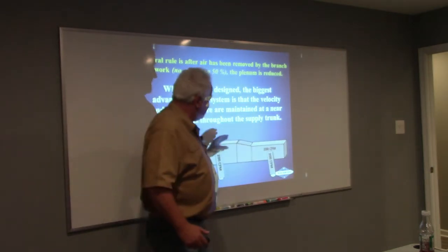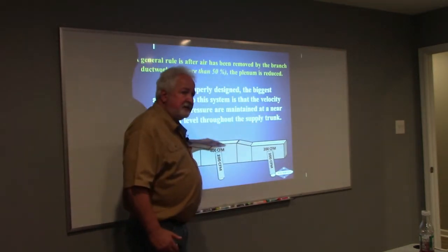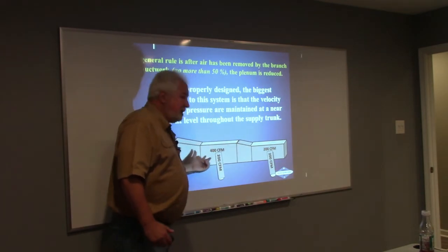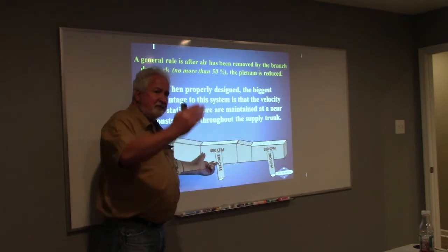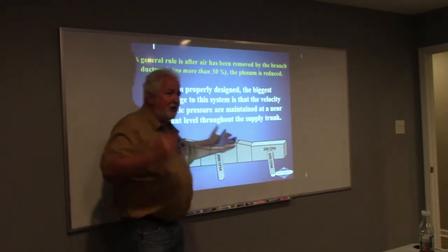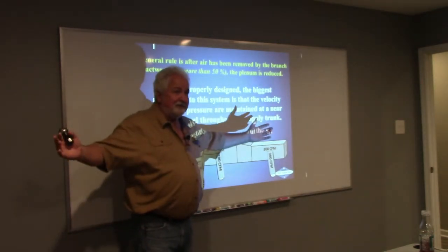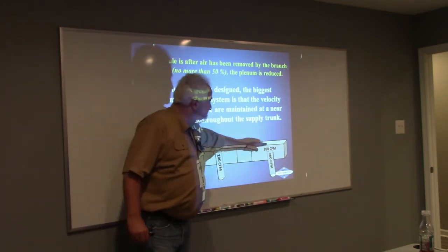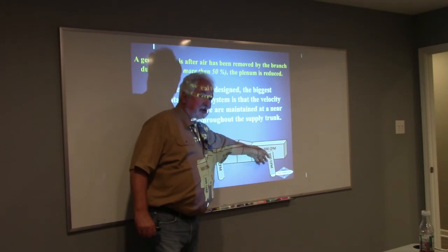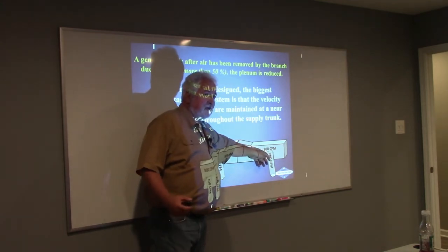I'm always sizing this next piece to how much air I have left. Remember we went from that 16 to the 14 to the 12? And we got to the 12 and we had 6 ducts down there at the end off of this 12. We didn't have enough duct left for our branch ducts. Does that make sense? Cool.